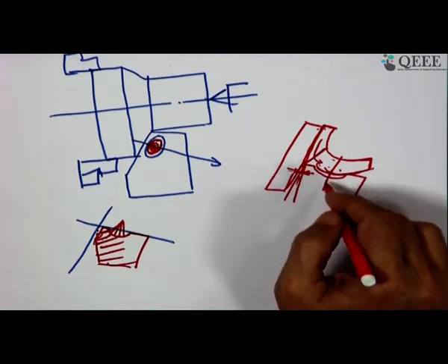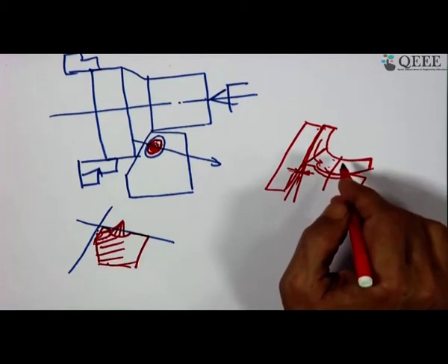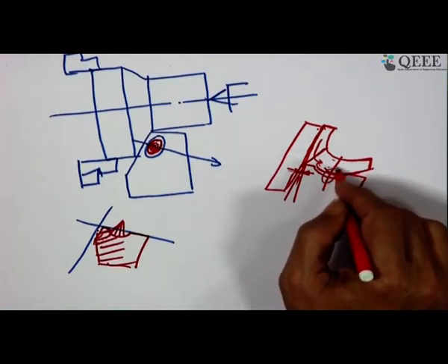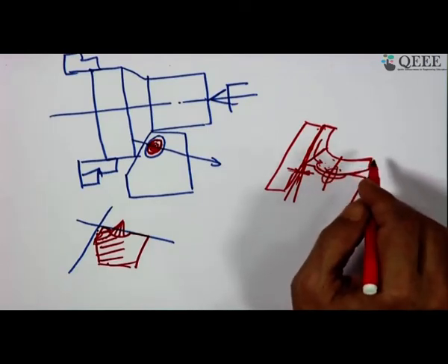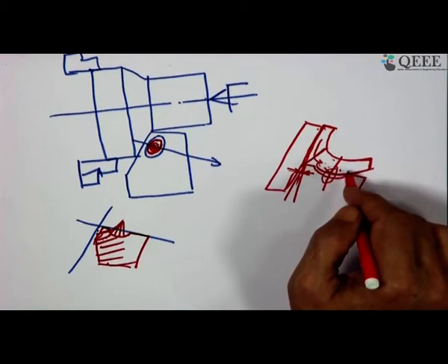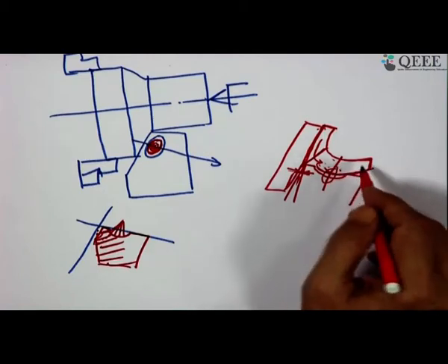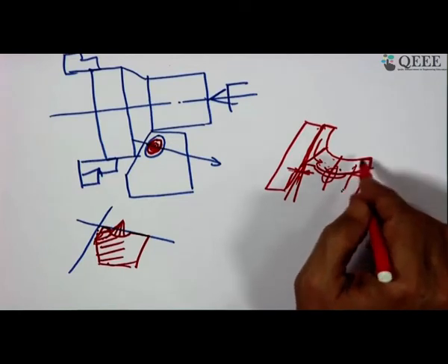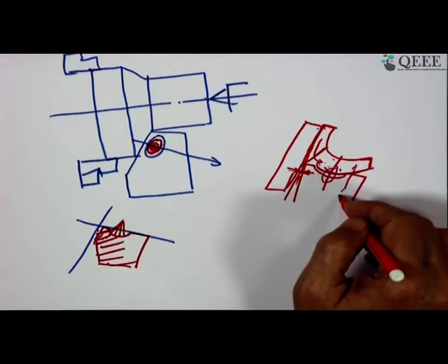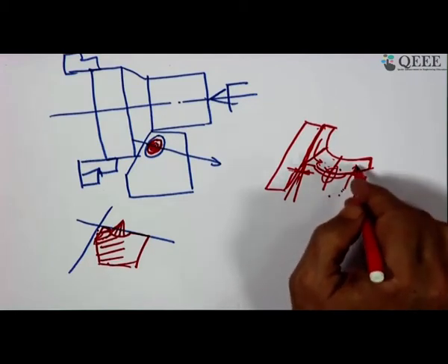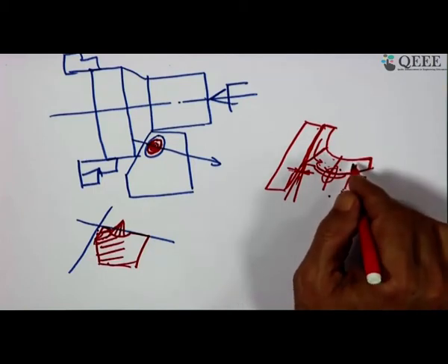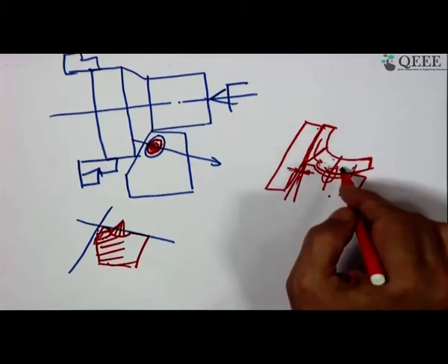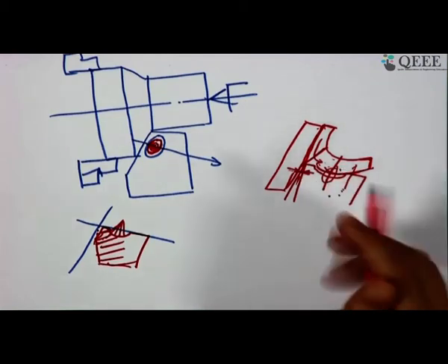So, chances of all sorts of chemically aggravated, chemically promoted wear will be high, and of course, one thing we assume is that in this case the chip is a continuous one, a ductile material, and you have a large concentration gradient between the materials on the two sides, which promotes the transportation of material from this side to this side, a large concentration on one side and absolutely no content of that material on the other. So, a high concentration gradient, then chemical affinity, temperature, pressure, which promote all kinds of dissolution or reaction.